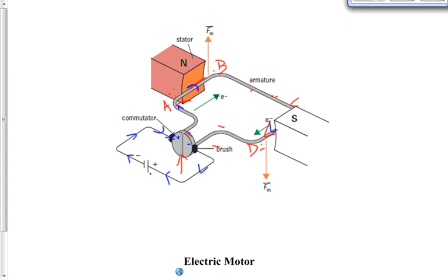That causes a force on wire, well, what's now DC, force on wire DC upwards, and a force on wire BA downwards. A quarter of a revolution, it breaks contact, and makes contact again as it goes through that quarter point. Now the current's going ABCD: up on AB, down on CD.